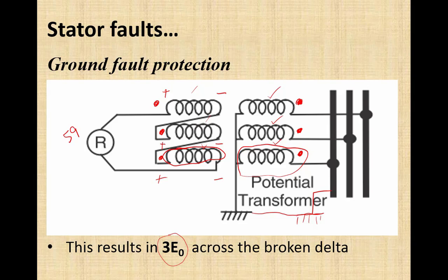Zero sequence currents and voltages will have the fundamental frequency, but the third harmonic and triplen harmonics will have a frequency that is at least 3 times higher than the fundamental. So next triplen harmonics will be, if even harmonics are there, the 6th, then 9th, then 12th, and so on. These harmonics' behavior is similar to the zero sequence.